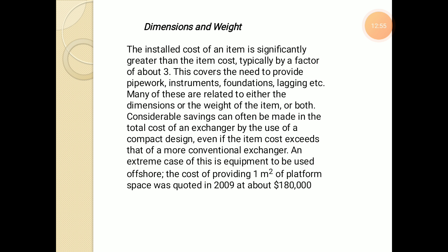Dimensions and weight. This is very important because a large heat exchanger is not preferable in aeroplanes, right? The installed cost of an item is significantly greater than the item cost, typically by a factor of about 3. This covers the need to provide pipe work, instruments, foundation, lagging, etc. Many of these are related to either the dimension or weight of the item or both.